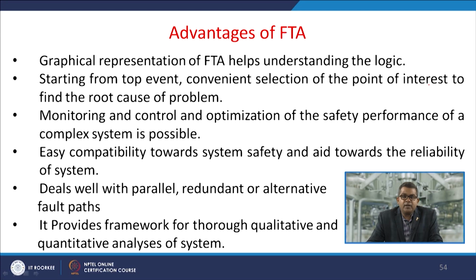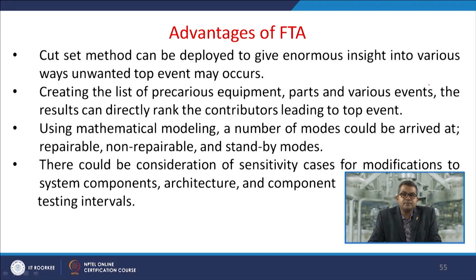Starting from the top event, it gives a convenient selection of the point of interest to find the root cause of the problem. The monitoring and control optimization of the safety performance of a complex system is usually possible under the head of this fault tree analysis. Now, easy compatibility towards the system safety and towards the reliability of the system. Now, it deals well with parallel, redundant or alternative fault paths. Usually, it provides the framework for thorough qualitative and quantitative analysis of the system.